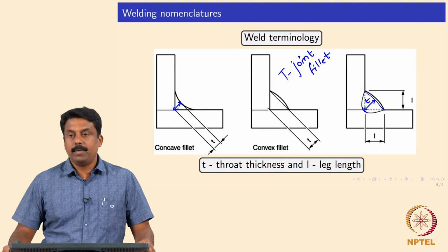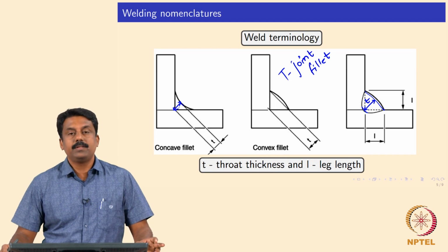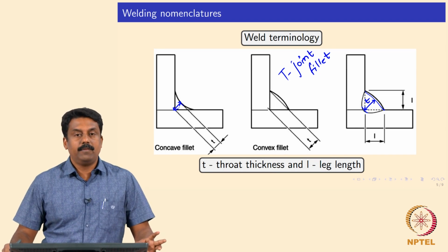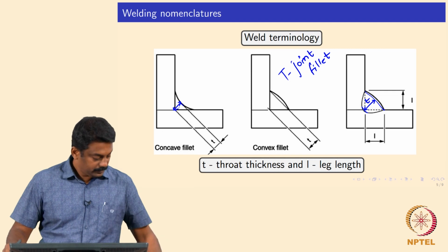Based on the thickness of the plates and the load bearing capacity, and the load which is going to be subjected during the commercial operations, we will have to make sure that we have calculated the throat thickness and length properly. Right? It's clear? Good.